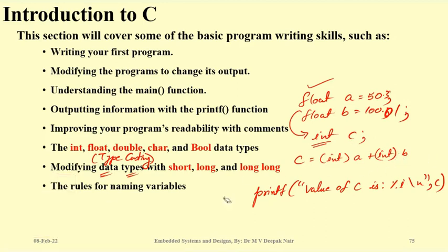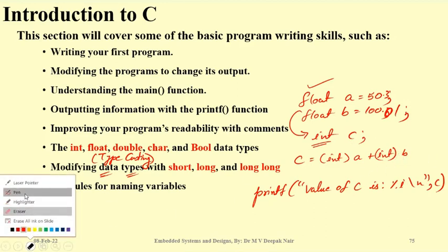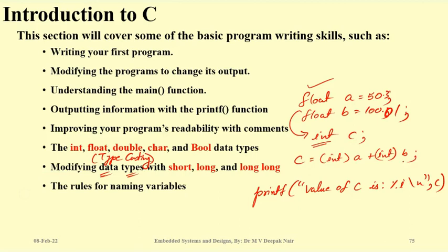This kind of stuff we don't generally do in our classrooms and courses. But most of the time it is very important when you are handling such variables in embedded systems, because I told you in the past also that a float type is managed by the FPU. Floating point units are specially dedicated for float variables.